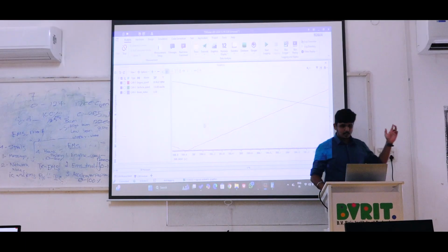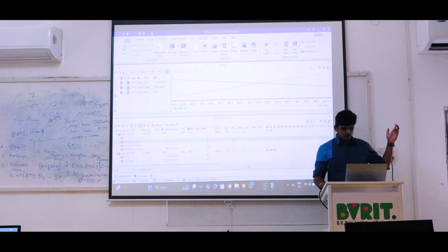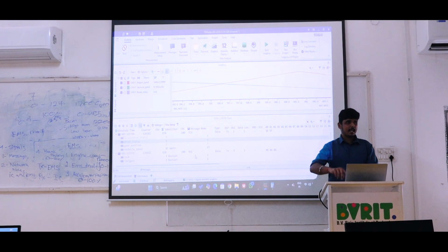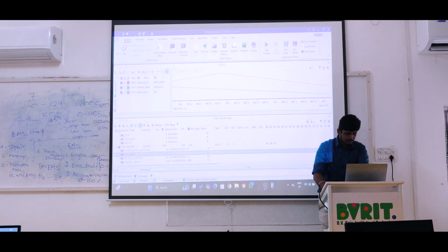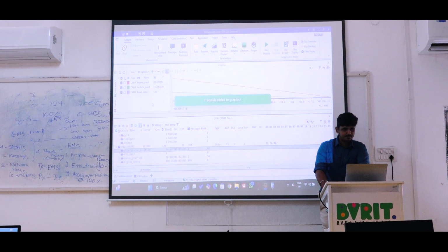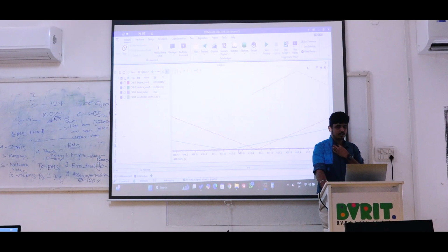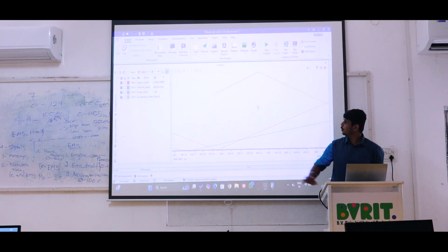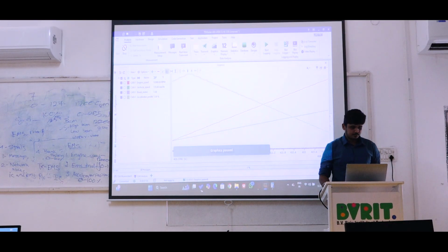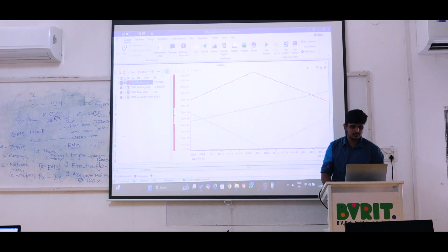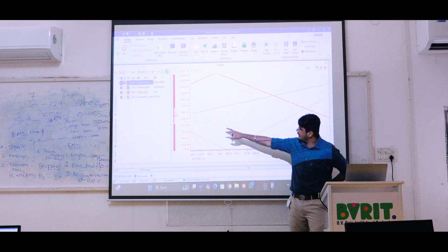Shortcut means nothing but I am just opening the trace window in parallel and dragging and dropping into this signal. Here I am dragging the accelerator position. See, here I am dropping. I can get the signal the same. If you want this x-axis also, you just need to tick the checkbox. It is engine speed. You can see it is engine speed.